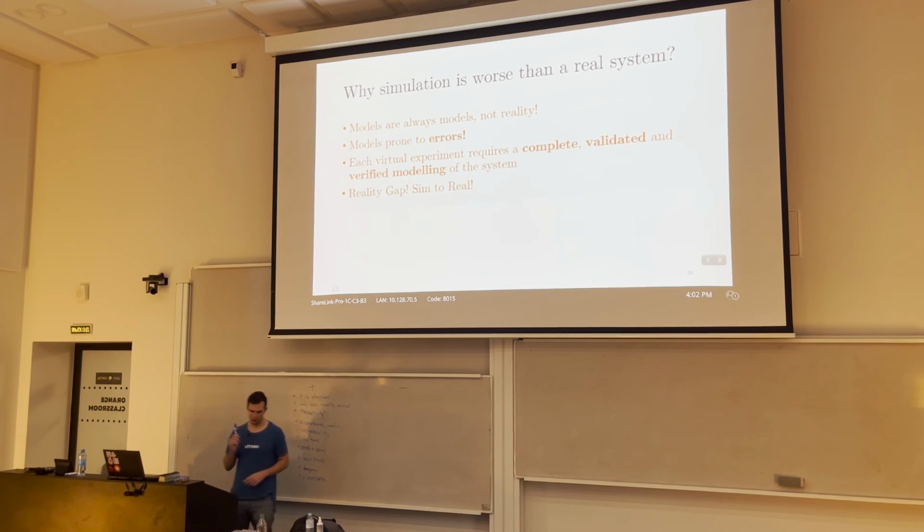For example, in the model of a grasping device that I just showed you, I modeled all parts as rigid, but then I printed the details out of PLA plastic, and the trajectories of the end effectors of the fingers were very different because of the elasticity of the parts. And it was not as precise as I wanted to make it, right?